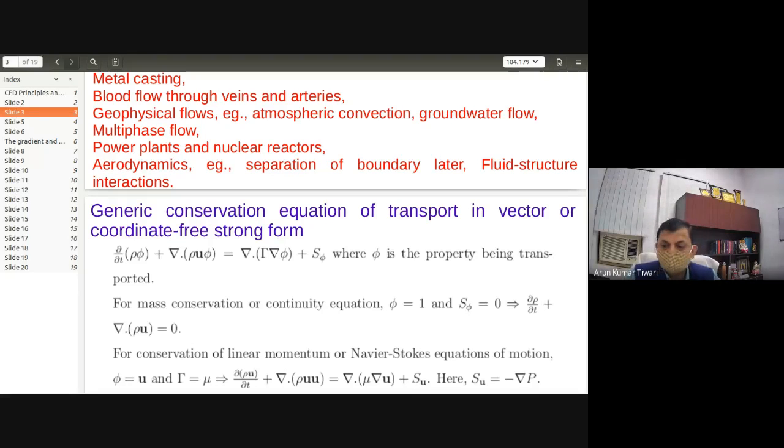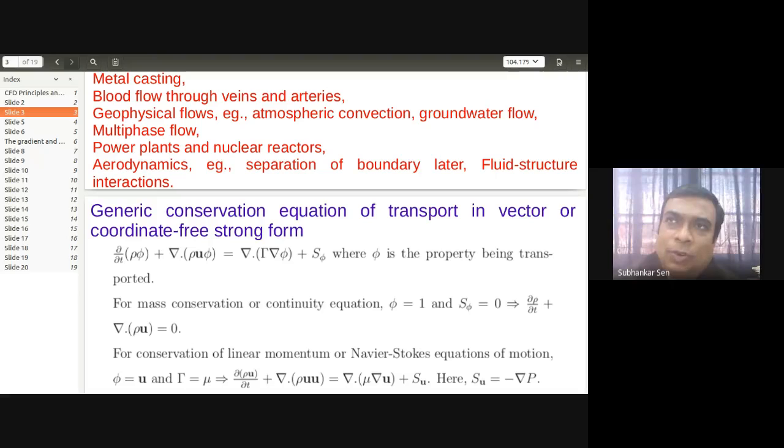At very low Reynolds number, in a highly viscous flow where the Reynolds number is very small, the convection term becomes very weak and you can discard it. For a Reynolds number of the order of 1 or much less than 1, you can remove this convective term, but in practical cases, the Reynolds number will always be large.